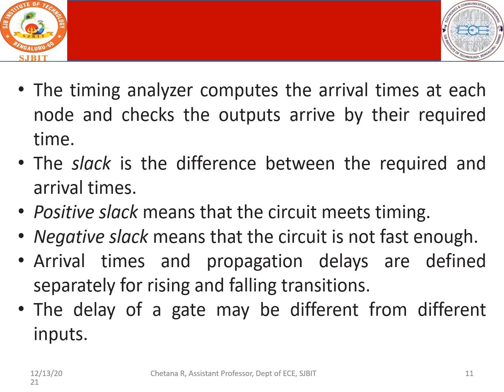Next we have another definition called slack. Slack is the difference between the required and arrival time. So I want an information to be passed within 1 second, but it is not happening within 1 second. It can happen for either 1.2 seconds or 0.8 seconds. Then the difference between them is plus minus 0.2 seconds. So positive slack means the circuit meets timing.